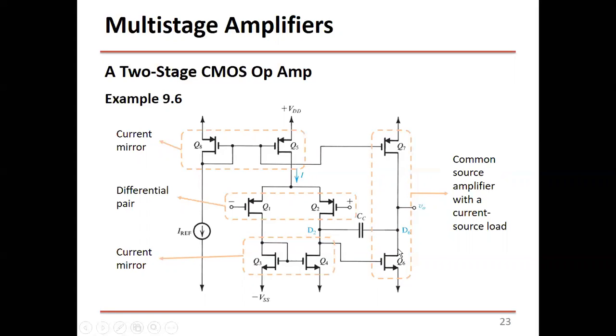And the drain is connected to, instead of a load RD, a current source. This is a part of the current mirror here, because the midpoint is also connected to this. So this is parallel to this, like if you assume Q5 and Q7 are parallel to each other. So the same current I will flow here. So we have a current here that's 90 microamperes, I believe.